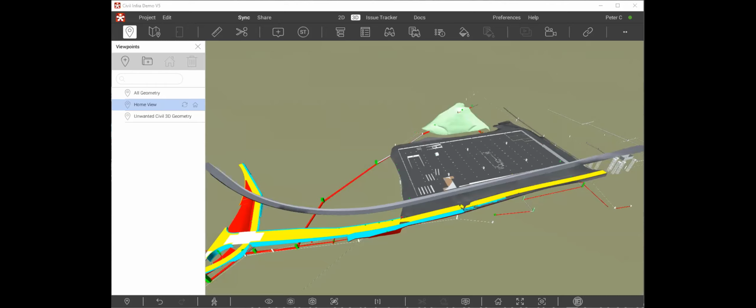You can use stamps, which is a slightly different subject, but you can set up predefined issues, create an issue for say a health and safety hazard, and allocate that and mark that up on the model and identify areas where risks might occur. So you could have a generic risk identifier or more specific ones. That would certainly be useful for principal designer duties.